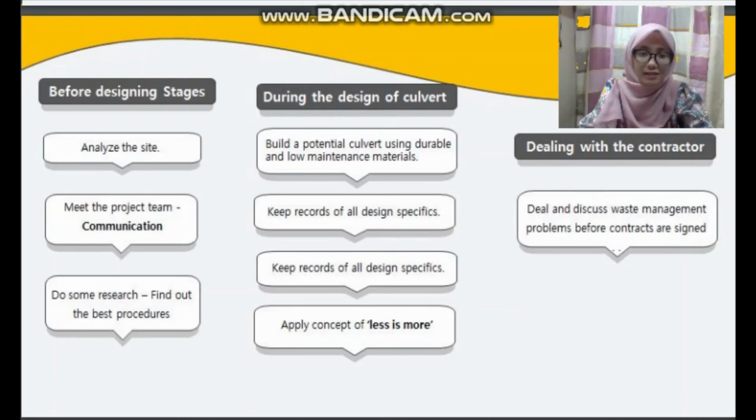And for the last is to build the culvert using durable and low maintenance materials, designed to make modification and repair simpler. In addition, we select materials and parts that can be reused and mounted in a way that allows screws to be disassembled instead of nails.